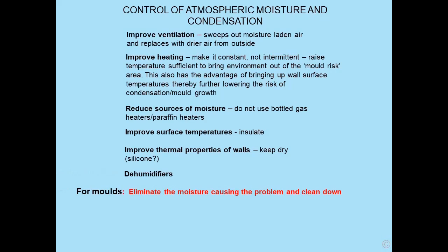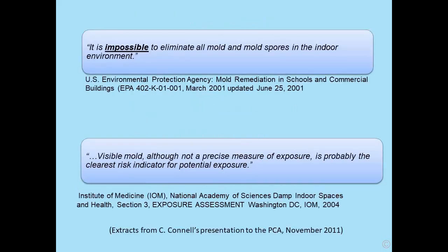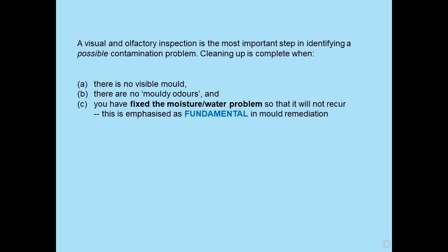But for moulds, we need to eliminate the moisture causing the problem and clean it down. It doesn't matter what mould is present, that is the fundamental cure for all moulds. And when we're looking at moulds, it is impossible to eliminate mould and mould spores in the indoor environment. And indeed, visible mould, although not a precise measure of exposure, is probably the clearest risk indicator for potential exposure.